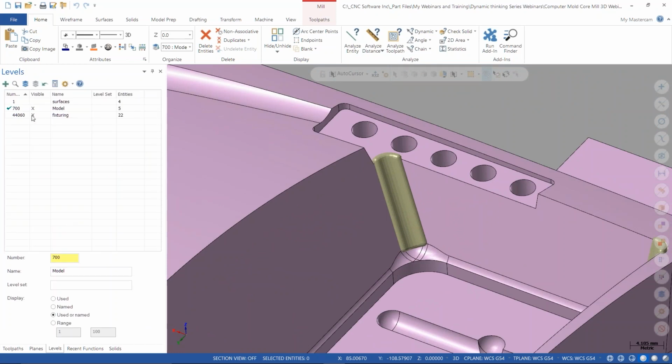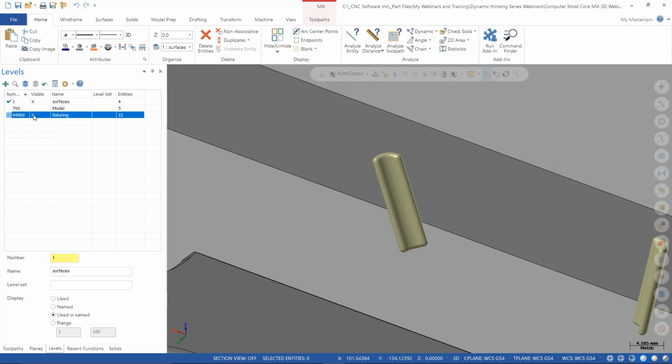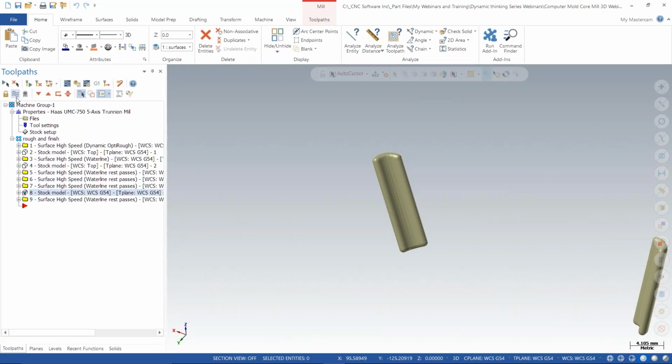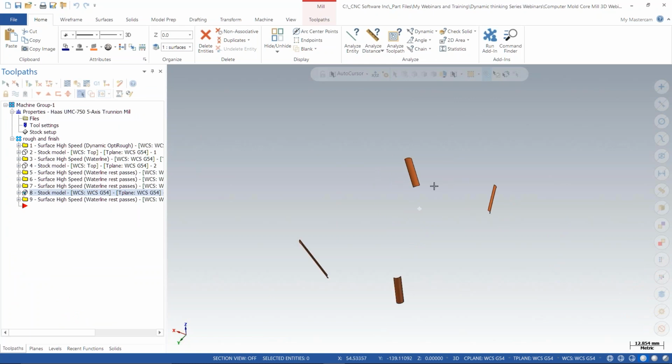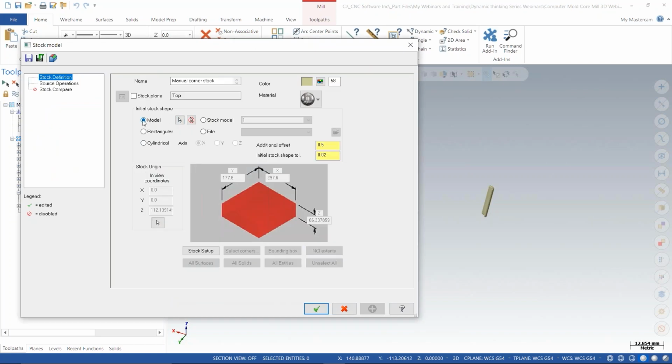And to do that, I went in and I had to convert a couple of these solid faces to surfaces. Let me turn this off for you. Surfaces, see? I can then create a stock model from model data, select those surfaces, and then I puffed them up 0.5 millimeter to give them a volume. I created those four shapes.